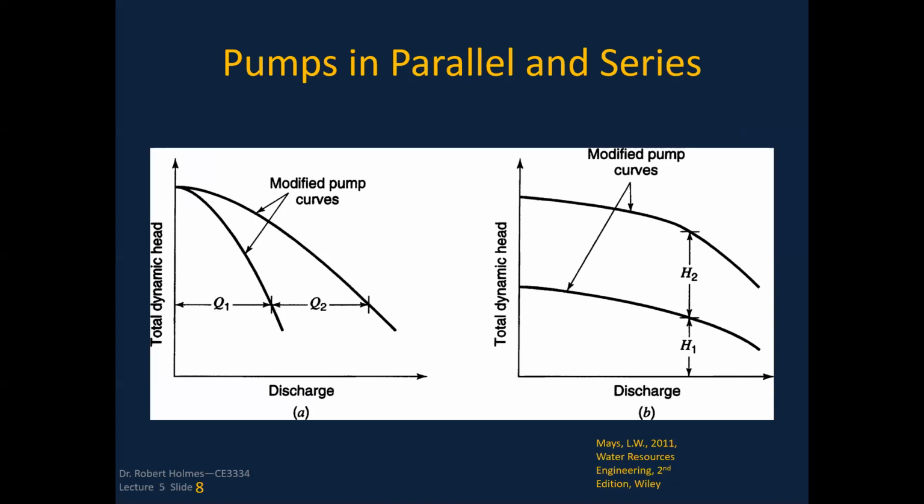If I had multiple pumps, and this is one thing that I've told you I'm not going to make you design for multiple pumps, but I am going to make you understand this concept. This is the concept of whether I've got pumps in parallel or pumps in series. If I've got pumps in series, I'm not adding any additional flow, I'm just adding head. If I've got pumps in parallel, I am not adding any additional head, but I'm adding additional flow.